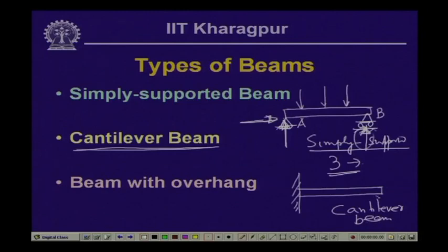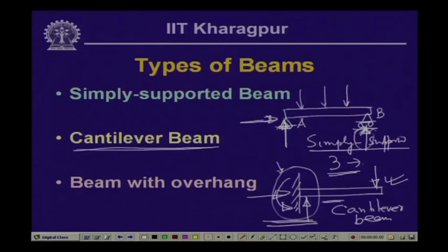Now, here when this is subjected to load, at this support, as we have seen in the fixed support, it is expected that there will be three reactive forces generated. One is the vertical force, one is the horizontal force, and another one is the moment. So, these three reactive forces will be generated at this support, and again if we look into this particular member, since we have three reactive forces, these three reactive forces can be evaluated using equations of statics, and hence again this member also is a statically determinate member.